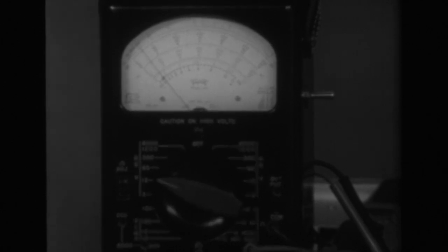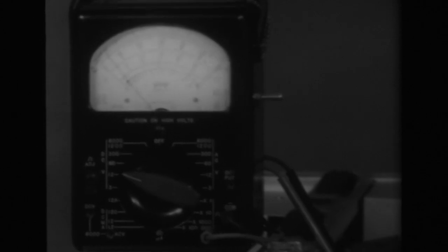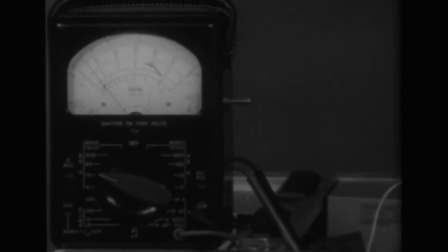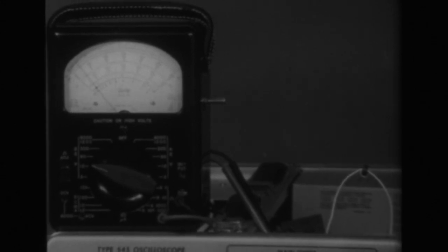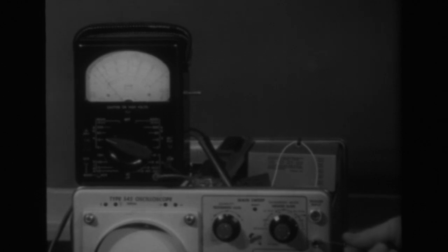So this tube is satisfactory as far as grid current is concerned, and we can then proceed with the rest of the adjustments. If you find that the meter changes on the 12 volt range more than 1 small division, it would be best to replace V8, that is the trigger amplifier tube, and let the new tube get thoroughly warmed up and repeat the adjustments to this point.